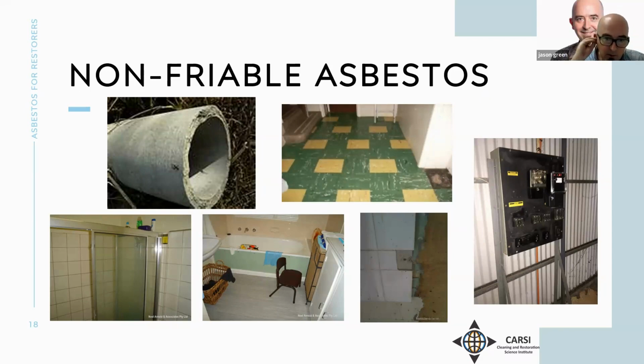So you can see down the bottom there some wet areas, very common in your kitchens and your laundries and bathrooms and showers. It could be asbestos sheeting on the walls, behind the ceramic tiles around the bath, for example. It's very common to be concealed behind those wall sheetings and floor sheetings. The floor underneath here may be a compressed fibre cement sheet if it's an older building.